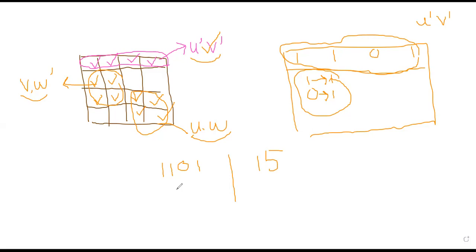When T is one, the flip-flop changes its state, and when T is zero, there will be no change in my system. There is a formula to find Q positive: Q positive equals Q XOR T. So it depends on the summation of two parameters. This is all about the toggle flip flop.